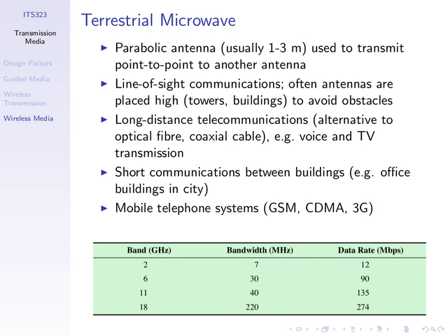But in fact, if the signal has a bandwidth of, instead of 7, say 10 megahertz, then the lowest frequency may be 1.995 gigahertz, and it may range up to a frequency of 2.005 gigahertz.